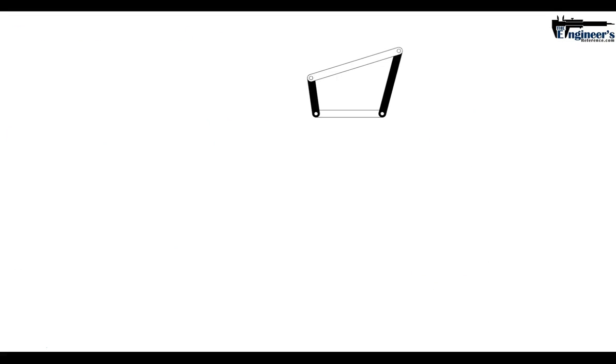Now again, let's look at this a little bit more. Now if we have the still picture and then we have it animated out, hopefully you can see how this looks more like a windshield wiper motion, where we got the shortest link next to a fixed link, and we got the longest link, and you're getting this complete rotation, and then you're seeing this rocking motion on this one. But let's go through a few things.